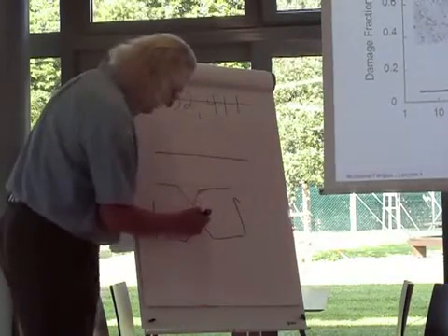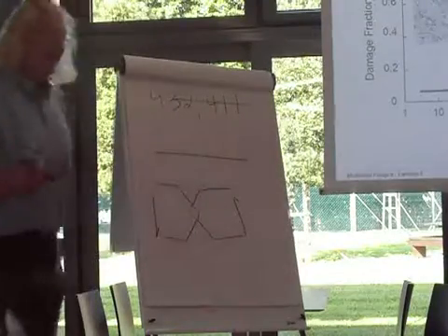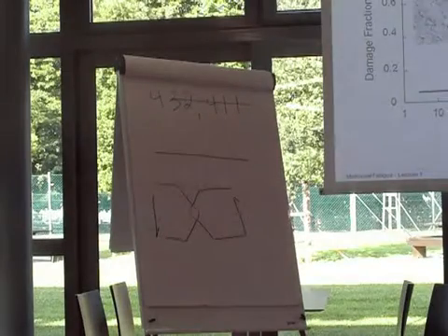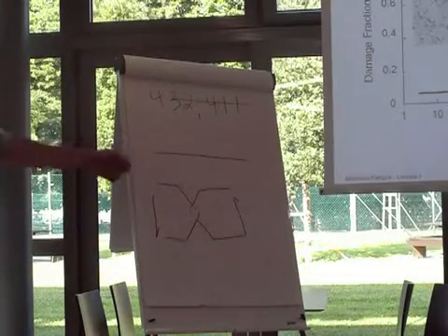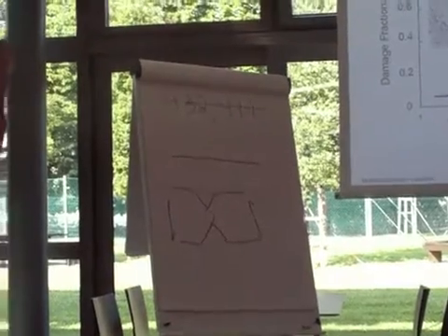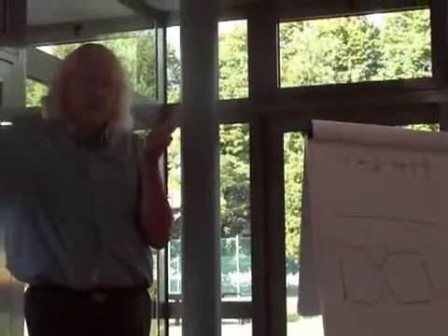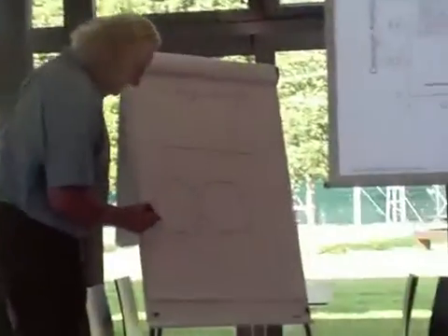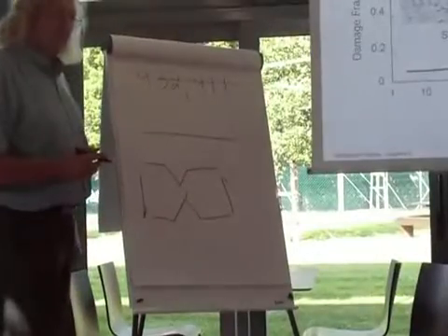And then, of course, this zone is in shear. And you say, fine, it should be really easy to grow a crack in shear. And if you believe the mathematics, that's true. But I spent about 5 years trying to do this in composites. Never successful. And the reason you are not successful is this is not the real boundary condition.